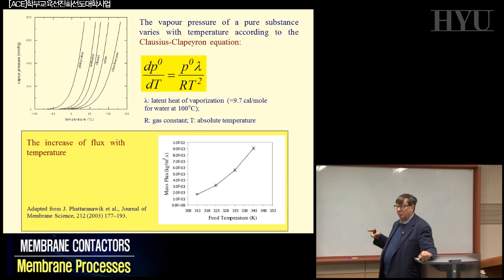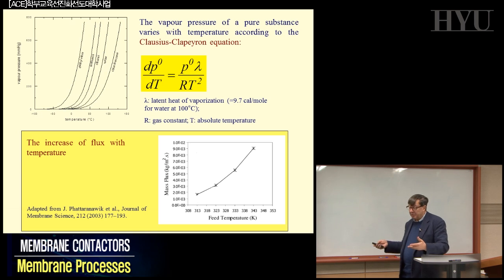Today, there are people trying to use membrane distillation not only for seawater desalination, which is a typical case, but to remove, I don't know, hydrochloric acid, some acid, or ammonia from some industrial solution, where there are salts that are not volatile at all, so they will stay, and you can remove some of the contaminants or some of the solvents such as ammonia, or acid, hydrochloric acid, a typical case, from salts. That is still at research level, but big companies are just testing this kind of possibility because traditional methods don't work as expected.